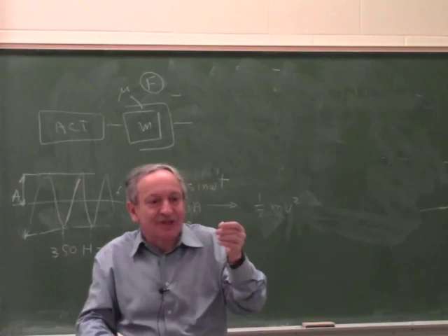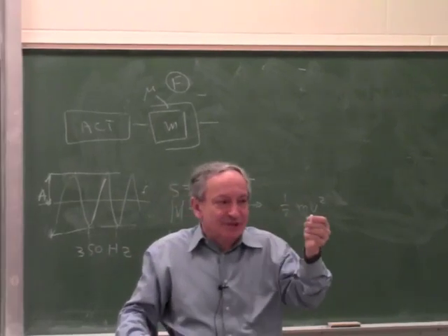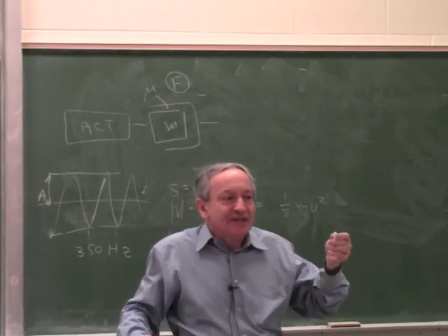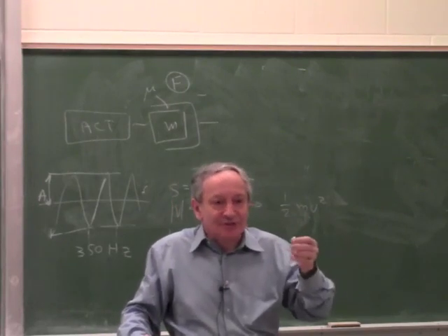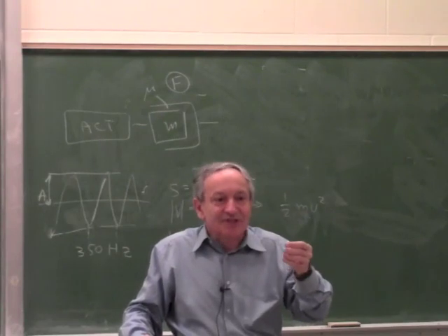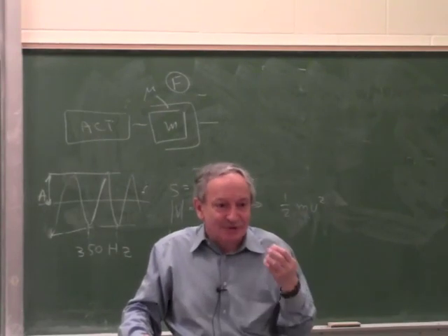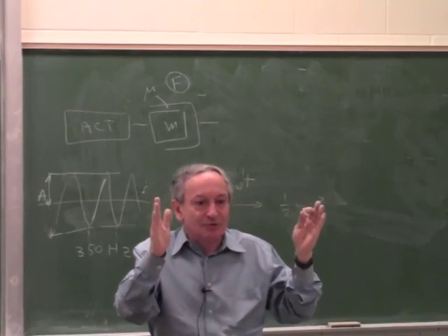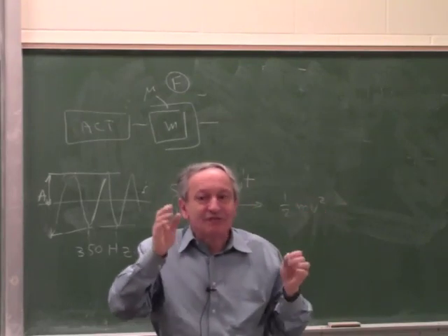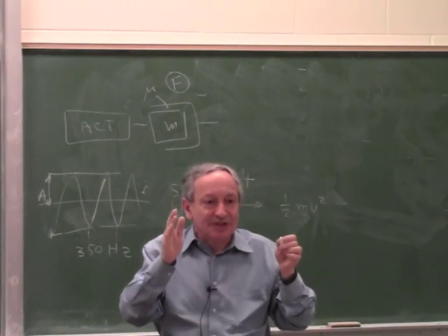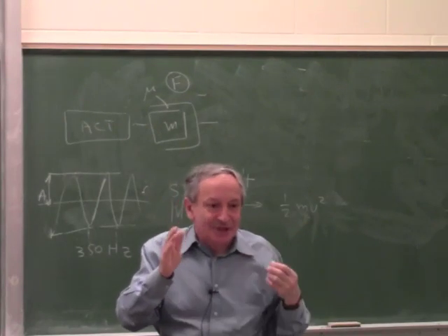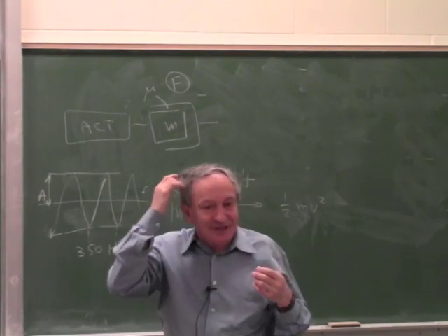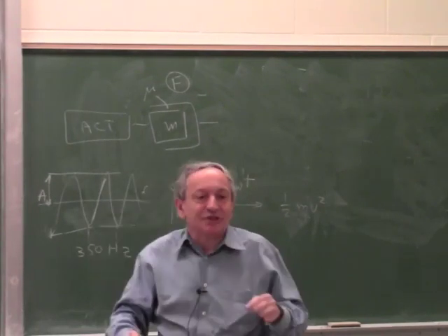It doesn't matter if it's not a sine wave. I have a mass and I move it fast, and I move it slow. But eventually, any acceleration I put into it is stored as kinetic energy. Eventually, this kinetic energy has to come back out, because I have to brake it, because the total position is constrained between two points. So every bit of acceleration I put in, which became kinetic energy, is still there, and I can get it back out. It doesn't have to be a sine wave. Think of an electric car which has no losses.